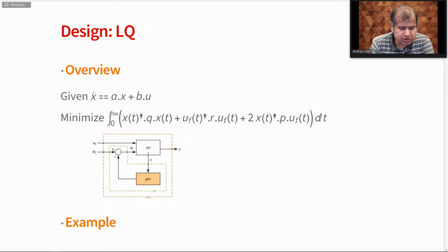And what this controller does is it's called a linear quadratic. So it's because it's based on the linear model, and it's minimizing this quadratic cost. And by driving these states to 0 and at the same time minimizing the control effort, the end result is it will stabilize the system. It will not only stabilize, it will also regulate the system to 0.